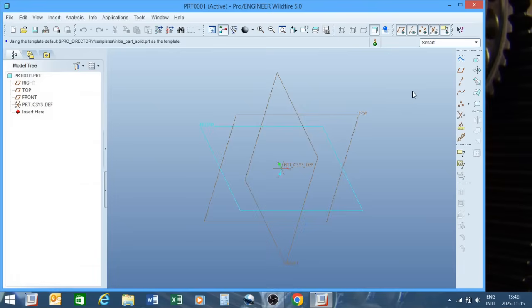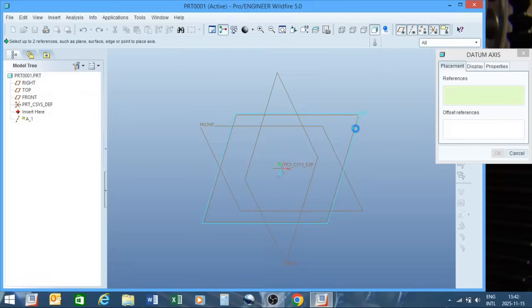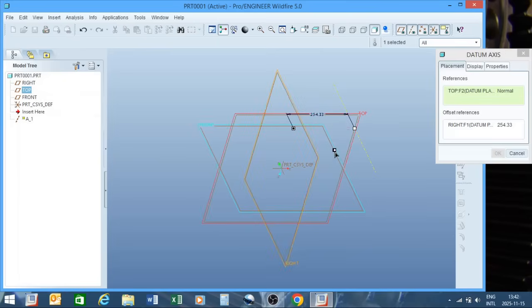So let's start. Today we're going to do revolve. The first thing I need to do a revolve, obviously, is an axis. So we're going to put in an axis. If I do an axis, I need to select the plane that the axis goes through. Then I need to select a plane to reference to and another plane to reference to. Obviously I need a left and right and up and down. So if we make these 0, then it will put it in the center of our sketch. So